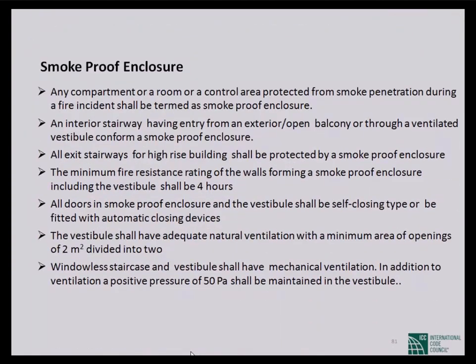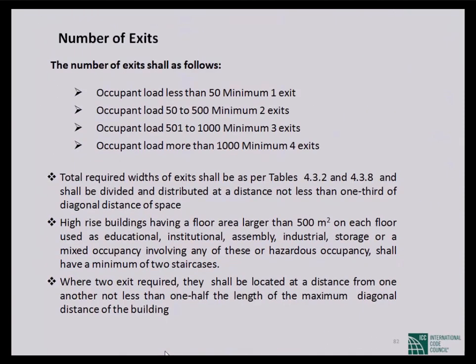Except for enclosure, you need a 4-hour rating. For a stair, you need a vestibule, an open area vestibule, to save the building. If it is a high-rise building, there will be a 4-hour fire rating for exit enclosure. These two you have to be careful about. And for the exit enclosure, you need fire pressurization, particularly in a high-rise building, and fire pressurization must be 50 Pa, 50 Pascal. So for a smoke-proof enclosure, all exits of the building must be smoke-proof enclosures.